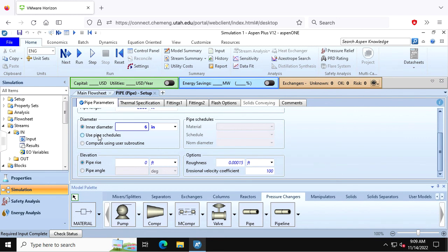In the US, when I say 6-inch nominal pipe, that's what it's called if you're using the pipe schedule. So if you go to Home Depot and buy a 6-inch pipe and take out your tape measure, there ain't nothing on that pipe that's 6 inches. I mean, it's true. The outer diameter of a 1-inch pipe is 1.3 inches.